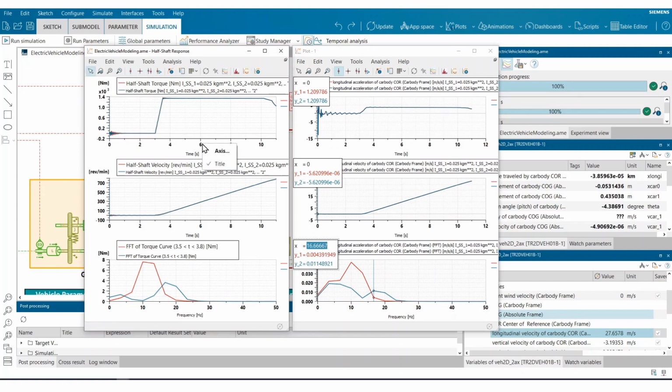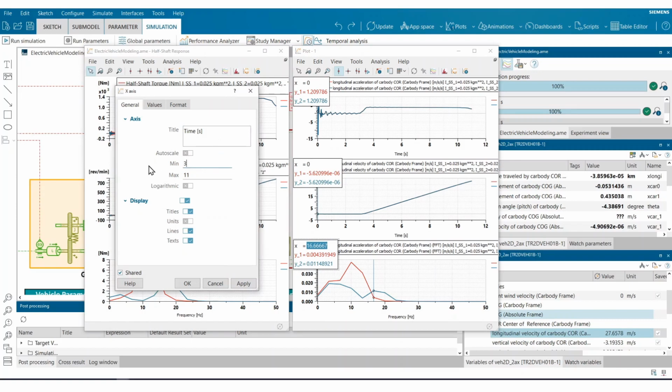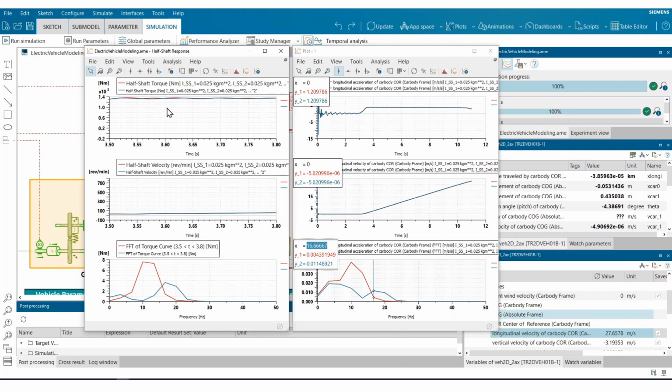We conclude that driveline oscillation during vehicle launch can excite driver interface location, leading to unwanted vibrations. An increase in drive shaft stiffness increases the frequency of oscillation and reduces the amplitude, where a similar behavior is seen on the C-track. In the case where drive shaft vibration amplitude is low, but a higher C-track vibration is observed, it may indicate an interaction with other system resonances, such as suspension frequencies. Further tuning and refinement analysis may be required in that case to evaluate the effects of systems interactions.